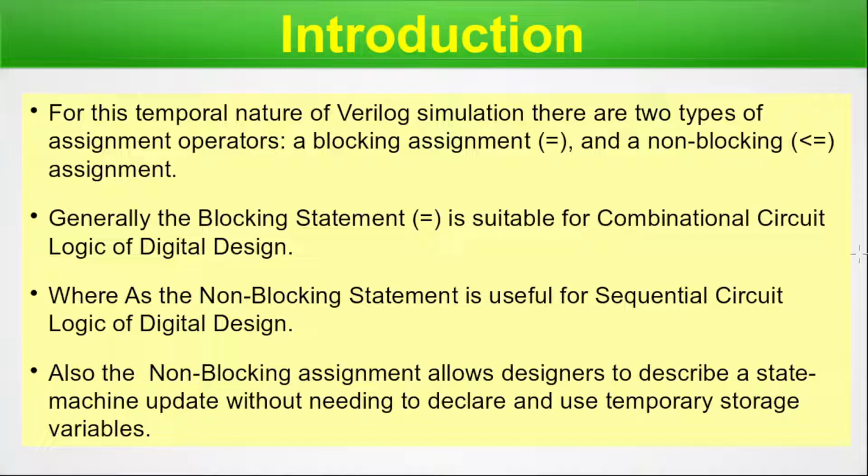Also, the non-blocking assignment allows the designer to describe the state machine, which updates without needing to declare and use temporary storage variables. So at some later episode, we will cover the state machine, and you can find familiarity with your already known circuits where the state machine is applicable. This is used for designing complex digital circuits and their states. There the non-blocking assignment is very useful. So for advanced VLSI design, the non-blocking assignment is a must. So here we are done with this particular slide. Let's move on to the next slide.